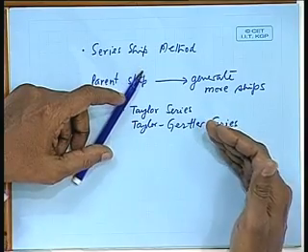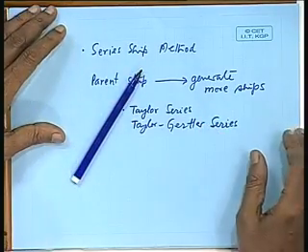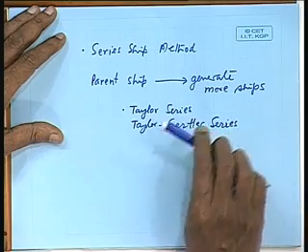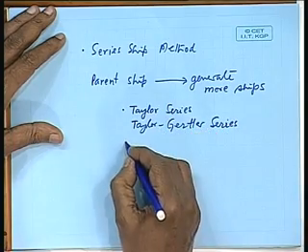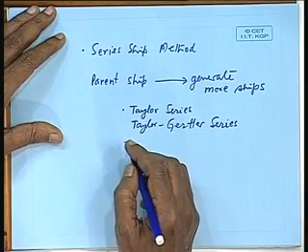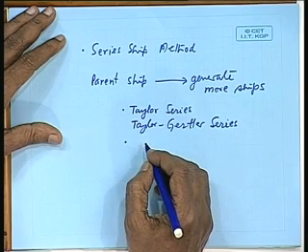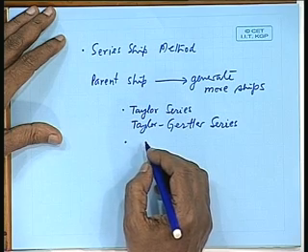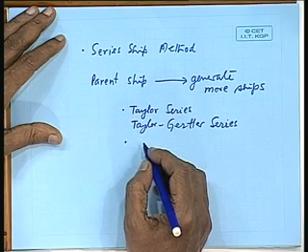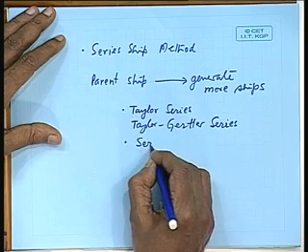Resistance is high. Naval vessels use it because they operate normally in 2 or 3 speed conditions, a sprint speed, then a normal speed, but merchant ships do not work like that. So, these vessels are not good for merchant ships, and so in the 1950s and 60s a series was generated in the David Taylor model basin of USA called series 60.